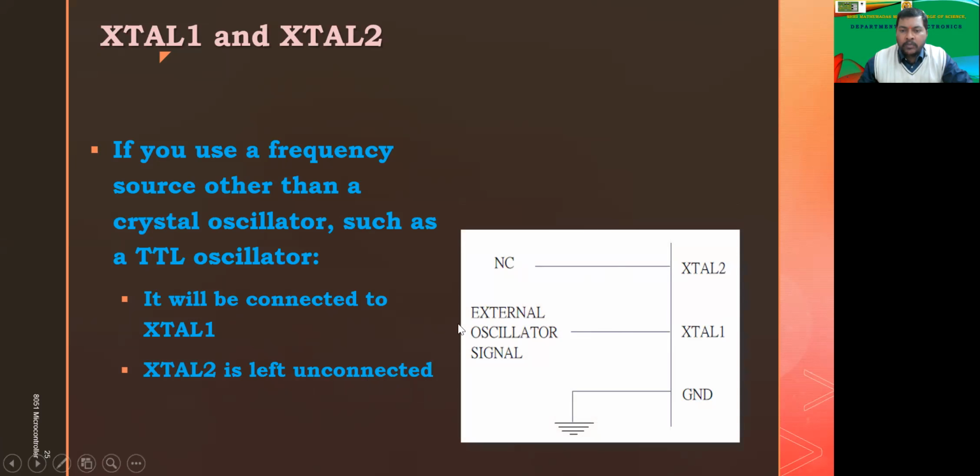So only XTAL1 is to be given. That TTL means transistor-transistor logic oscillators can be used over here. And instead of using the crystal oscillator, if you are using the crystal oscillator, then both the terminals should be used, right? So one by one, and this is a ground.